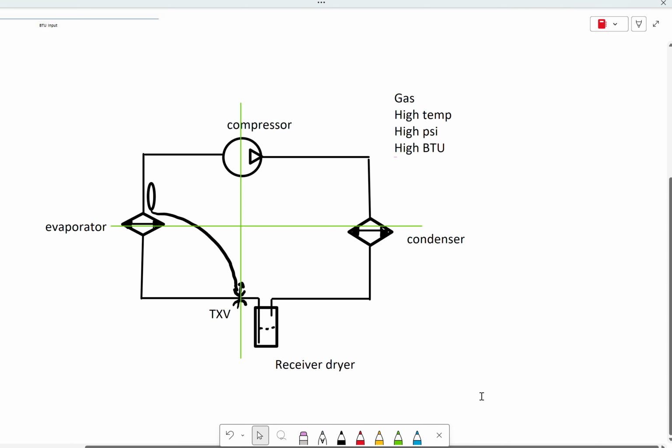If we come down here and we run it through the condenser, what happens? Okay. So we're going to try and remove heat energy from that vapor. And when you do that, if you get enough heat energy removed from the vapor, what happens to it? State change. So we're going to try and turn it into a liquid here, right? Now, are we really trying to achieve a huge amount of temperature change here, or are we just trying to get the phase change to happen? Phase change. So the temperature here is irrelevant. It might be pretty warm. It might have cooled off a bit. It just depends on what the ambient temperature is relative to what's happening in the system.